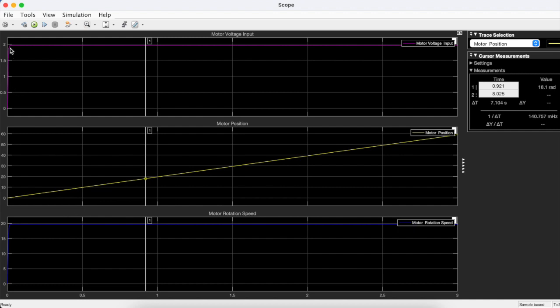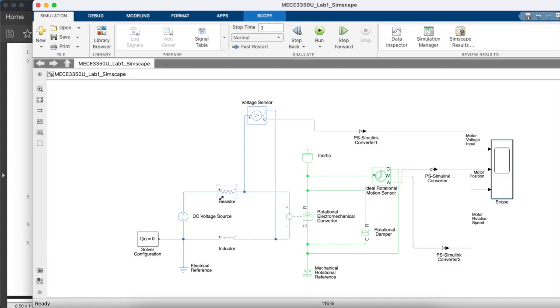So here you had this voltage input of 2 volts. And you see that the output is actually half of what it was in the Simulink model. So this means that there's actually probably some parameters that are different between the two models, as both models should give about the same response. And so this one says 20 and not 45. And so now let's investigate which of these blocks is different between the two systems.